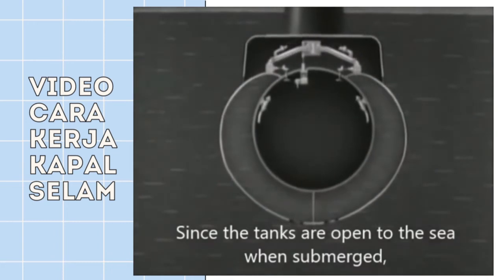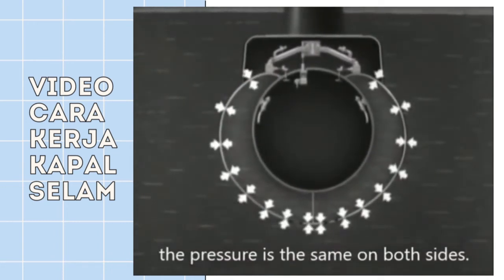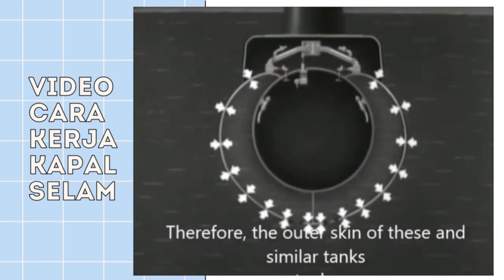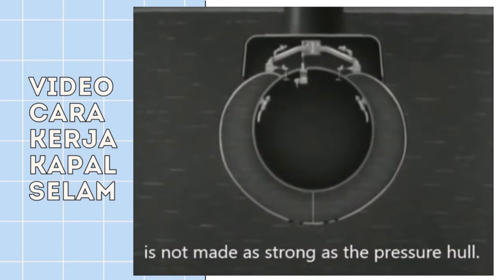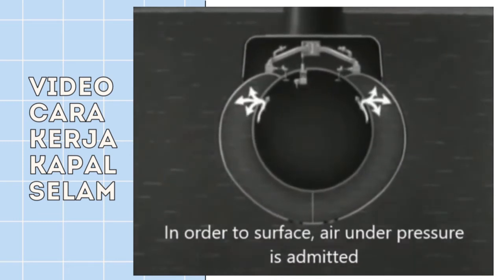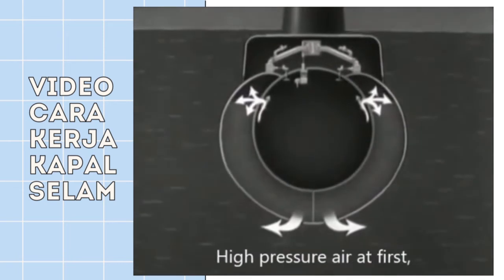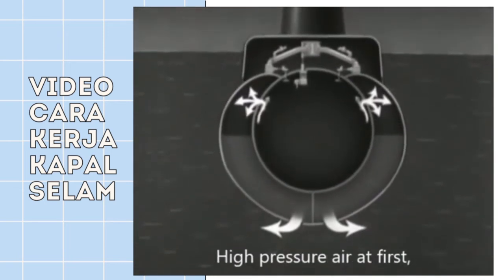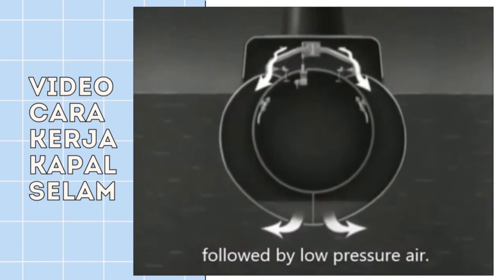Since the tanks are open to the sea when submerged, the pressure is the same on both sides. Therefore, the outer skin of these and similar tanks is not made as strong as the pressure hull. In order to surface, air under pressure is admitted to blow the water from the tanks. High pressure air at first, followed by low pressure air.